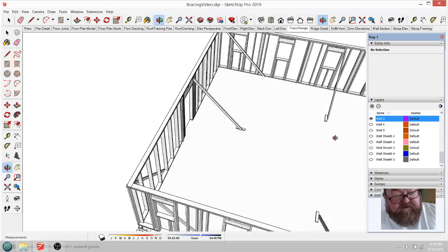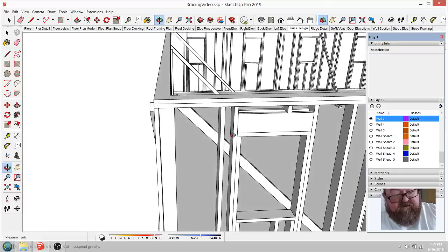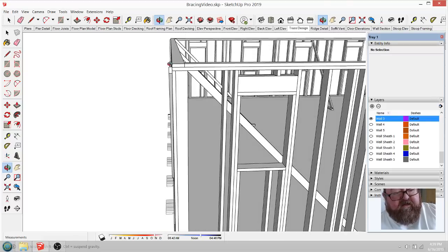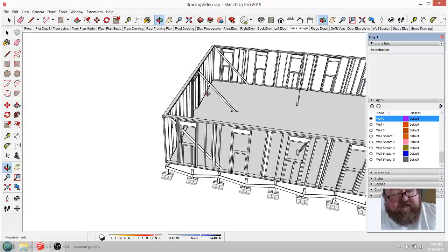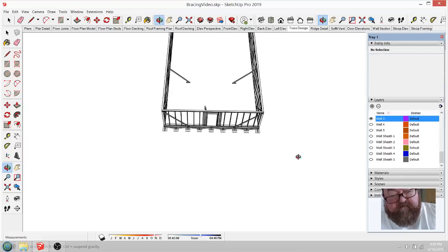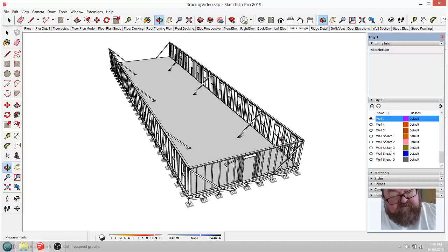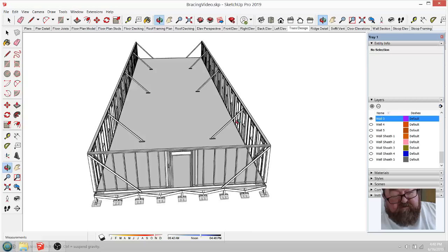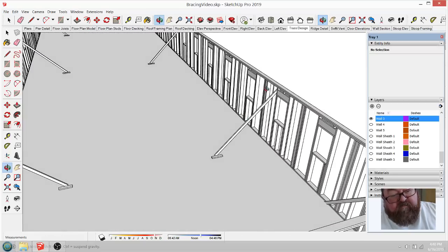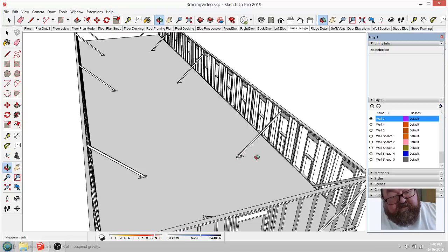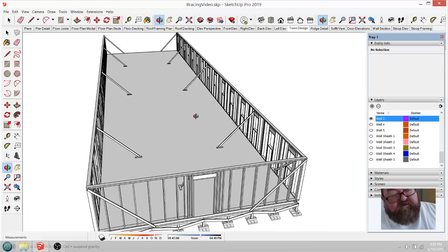And you're straightening the walls too. I meant to mention this. Before you nail these braces off, you want to look down the wall, pull a string down the wall. It might be a little early, but you want to get the wall halfway straight before you nail these braces off. You want at least somebody eyeballing it, because before you put your roof trusses on, you're going to pull a string down this long wall, and you may have to loosen the nails in this one and push the wall in or out. It's hard to get them straight until you get all your walls up.